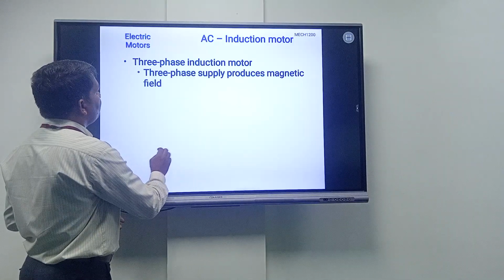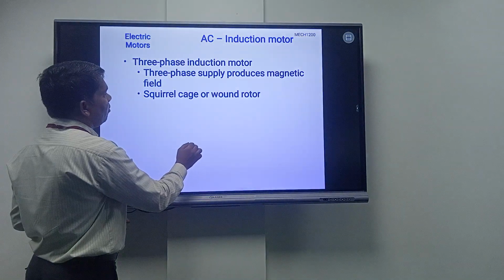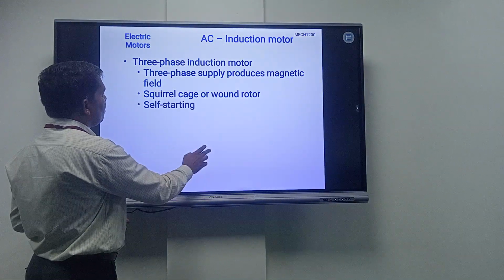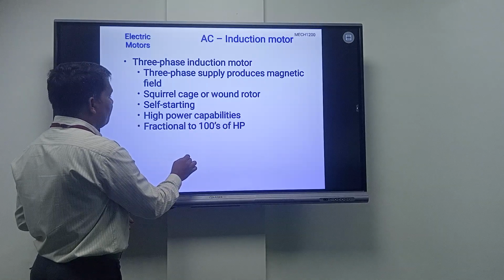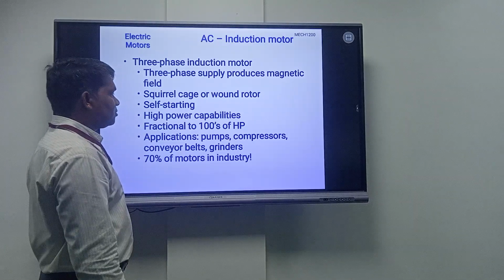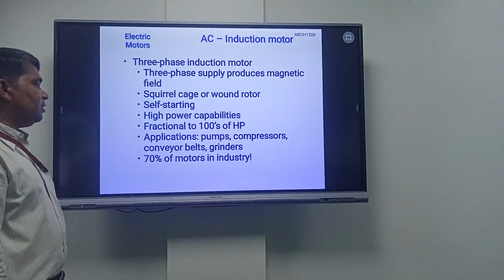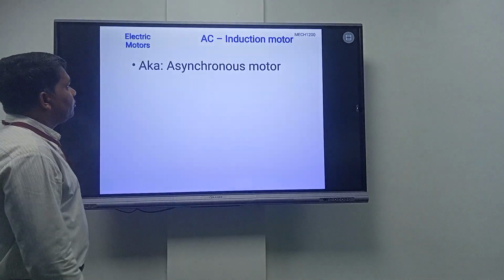Three-phase induction motor: 3-phase supply producing a magnetic field, squirrel cage or wound rotor, self-starting, high power applications, fractional to 100 horsepower applications, pumps, compressors, conveyors, belts, grinders. 70% of motors in industries are this type, right?